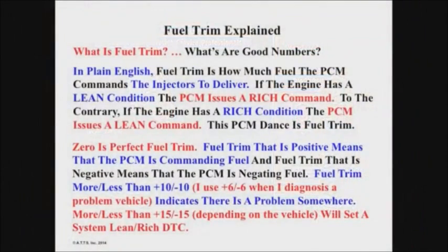Okay, fuel trim. This is an important thing. Because of the amount of time we have, I can't get deep into it, but you should all know fuel trim. What are the numbers you look for? Basically, if you're at a 10 range, you're going to run into problems. You need to look at fuel trim very, very carefully. On the IDS, what does Ford tell you for the mass airflow sensor? You guys ever do the contamination test? They go right in to show you fuel trim instantly. You know why? It's the most important thing that's either going to kill the cat or let the cat survive, right? So fuel trim is very, very important.